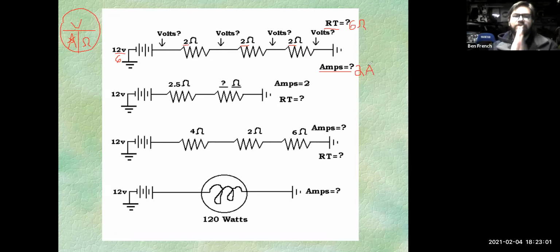So remember, the rules of a series circuit always play into that circuit, right? One of the series circuit rules is that the current flow is always the same throughout the circuit. And if you remember, that current flow is the flow of electrons, right? So if I have 2 amps worth of little electrons flowing out of the battery, they've got to still be flowing here.